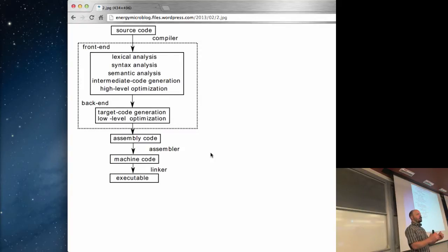So if you write C code, there really is an equivalent between what you write in C and what you will later on see in assembly. Now, depending on what level of optimization GCC does, this can be almost unrecognizable. Or sometimes it disappears because GCC recognizes that some of your code was not written very well, or did something that was not useful, and so it just removed it to speed up the process. Now, in embedded systems, this can often be a big problem for you, because sometimes you do things that the optimizer doesn't understand are really what you want to do.